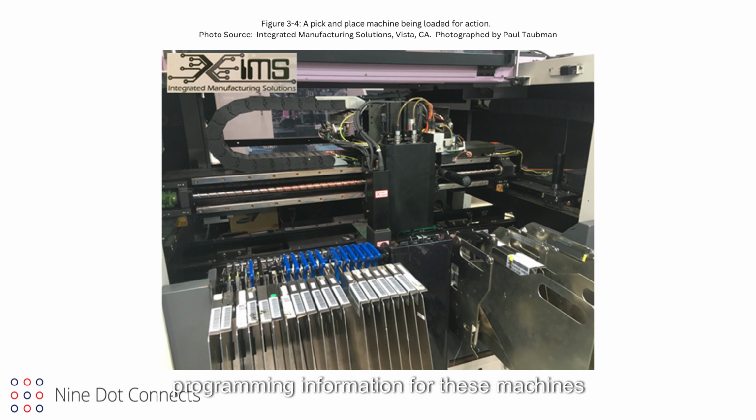The programming information for these machines comes from the pick-and-place files that are produced by EDA tools. An X, Y, layer, and rotation position is given for each component on the PCB. These inputs are compiled into the machine programming language to drive the machine placement heads. The machine compilers also optimize the input data for the most efficient motions of the pick-and-place heads. Companies that make pick-and-place machines have videos online to advertise their capabilities. Such videos are certainly worth a few moments of time to see these amazing machines in action.